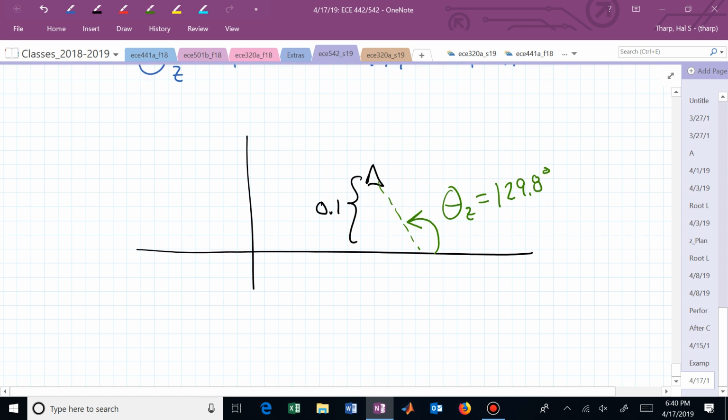I know that triangle is right over the top of 0.9. I'm now wanting to find this distance, I can call it x bar, for the location of that 0, which is at beta. By trigonometry I can find x bar. I know the angle, I know the vertical distance, I'm just trying to find the horizontal distance. And once I know x bar, I can find beta.